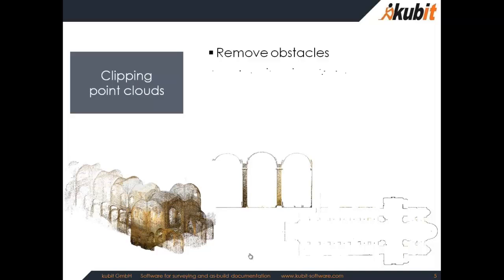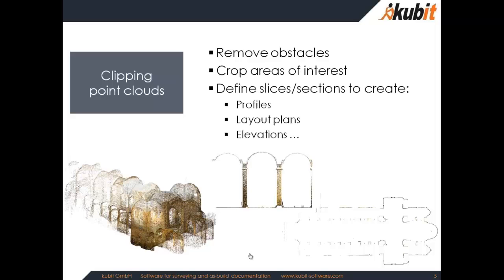You can clip the point clouds in order to remove obstacles. You can crop areas of interest. You can define slices and sections to create profiles, layout plans, and elevations. Very similar to what you could see in PointSense Building if you joined the previous part of the webinar.